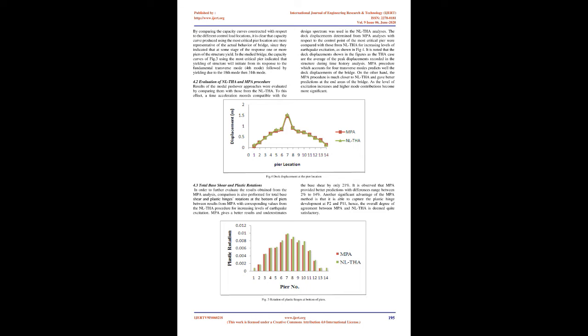All nodes lie at the same elevation, at the center of gravity of the girder and stringers, and mass is lumped at both ends of the element. Each pier is modeled as an element with an elastic-plastic behavior. It is assumed that the piers will fail in flexural mode, where a plastic hinge forms at the pier's base.